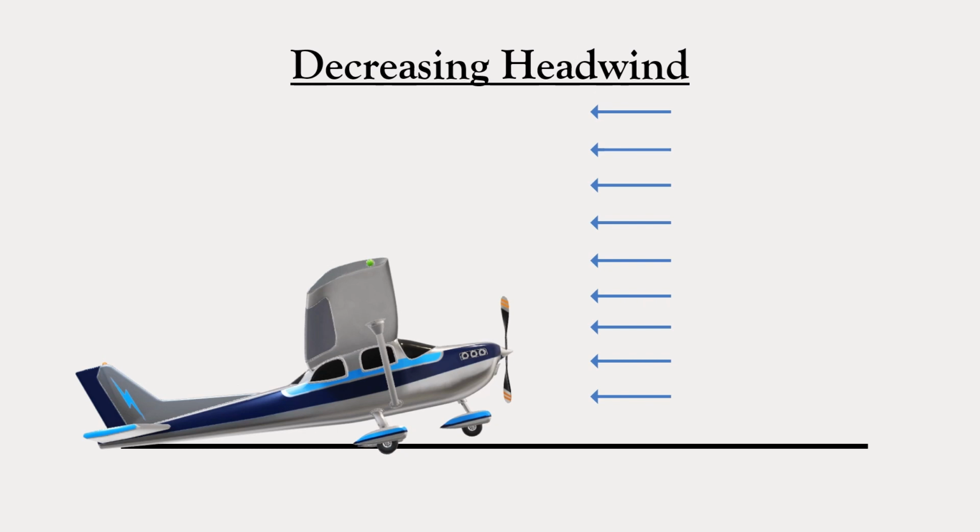So is it a big problem that the airplane came back to the runway? Well, that depends. If the airplane started to drift sideways or to yaw while it was airborne, then when it comes back down and hits the runway, there will be side force on the wheels. Remember that it's not uncommon for there to be a crosswind gust happening around the same time as this headwind change.